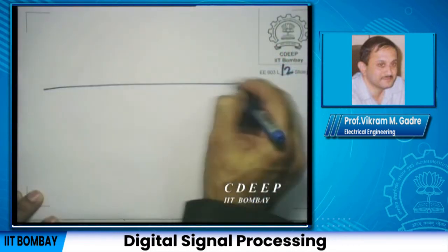Is that correct? If you take this restricted Fourier transform band limited signal and sample it at the integer points, you are sampling at a sampling rate of 1. What would happen in the Fourier domain? You would take the original spectrum, translate it by every multiple of 2 pi and add these translates. Let me try and explain graphically. I am saying this is the DTFT.